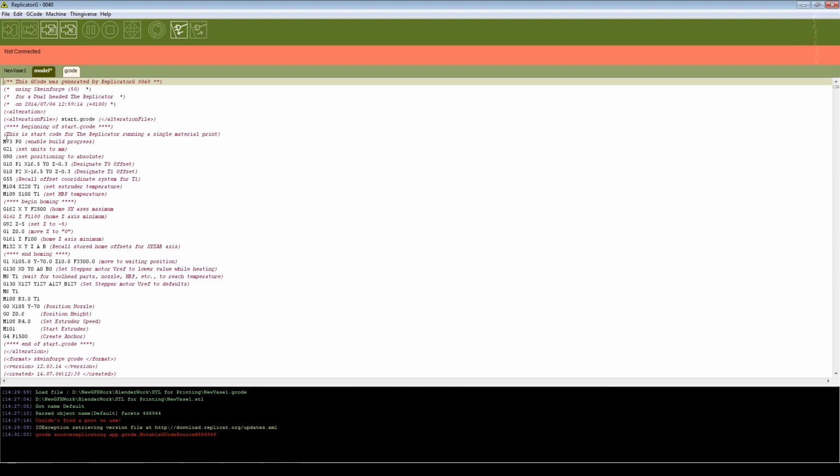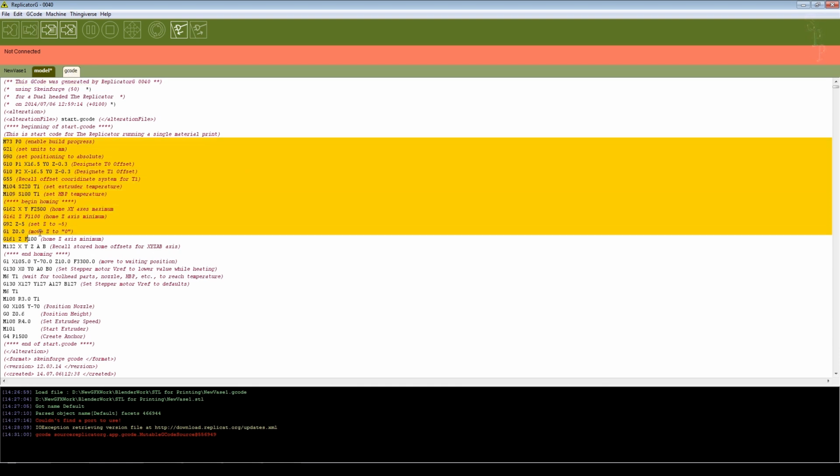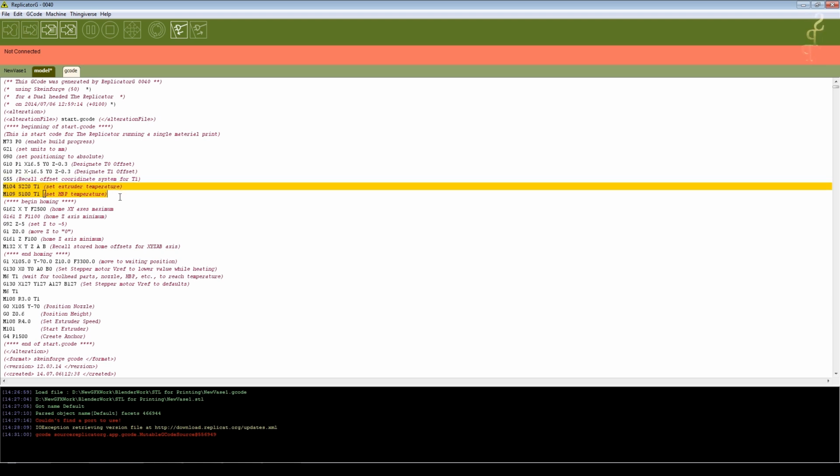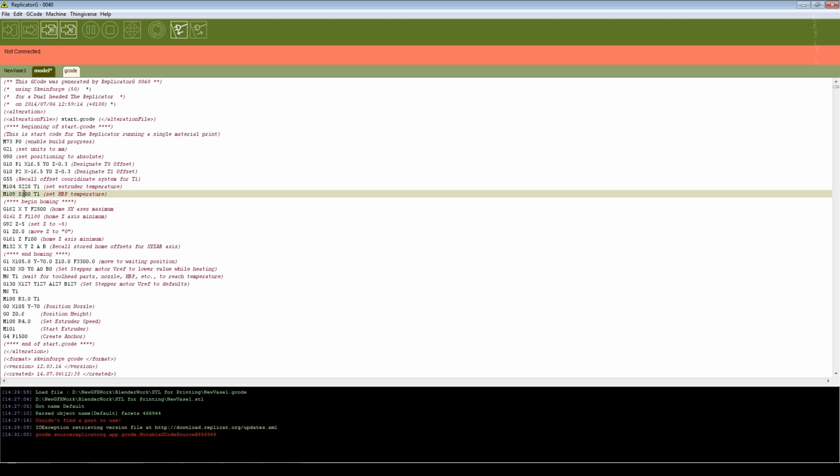Now you can get crib sheets that tell you what all these codes mean. The writing in the red here is just reminders of what it means, aide-memoires, but the ones that I often play with are down here. So you can see, for example, here HBP means heated build plate, particularly if you're printing in ABS, but not just in ABS necessarily. In order to help it stick to the print bed and to minimize shrinkage, you typically heat the build plate.